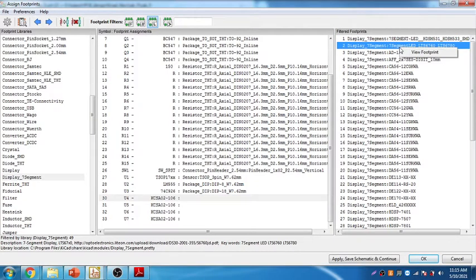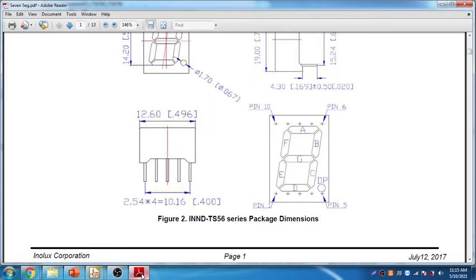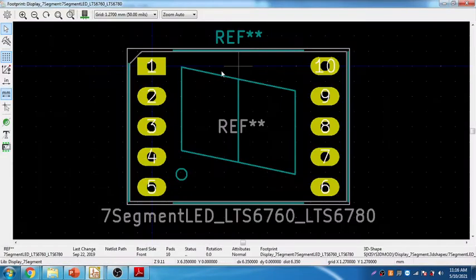So these are all different kinds. Hopefully this could be possible. You see this 7-segment display, it is 1 2 3 4 5. We need to find out the distances once. As per the data sheet, if you look into this, the pin to pin is actually 15.24. So I need to find from this pin to this pin, 10, is 15.24. That should be the case.